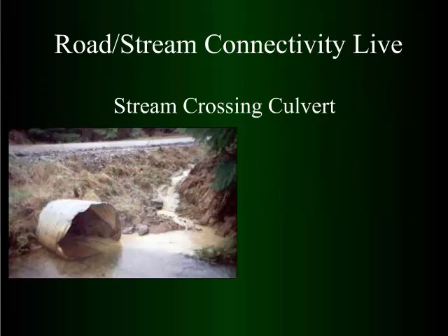Another example of ditch water, a lot of ditch water coming in. You can see that it's carrying a lot of suspended sediment and dumping it right in the stream and then headed down the pipe. A situation where somewhere up the ditch line that water needs to be taken off and deposited in an area where it can filter before it actually reaches a stream.